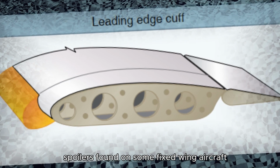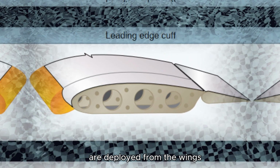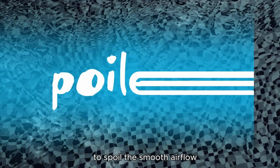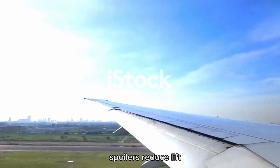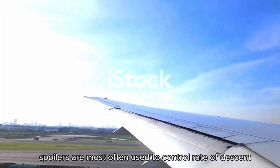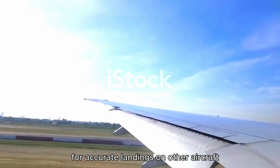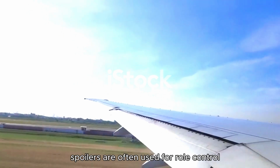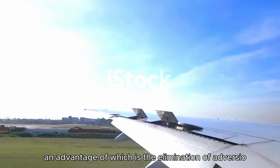Spoilers. Found on some fixed-wing aircraft, high-drag devices called spoilers are deployed from the wings to spoil the smooth airflow, reducing lift and increasing drag. Spoilers reduce lift and increase drag during descent and landing. On gliders, spoilers are most often used to control rate of descent for accurate landings.